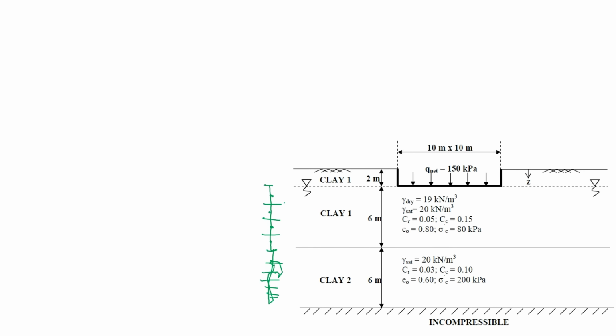Then you will repeat the same procedure and apply different formulae as per the conditions of first case, normally consolidated or over consolidated, case 1, case 2, and then you will add. If you have converted 10 layers, then you will add the results of these 10 layers, SC3 and so on up to SC10. Then you will get the total consolidation settlement. That will be near to 172 millimeters, but that will be more precise.